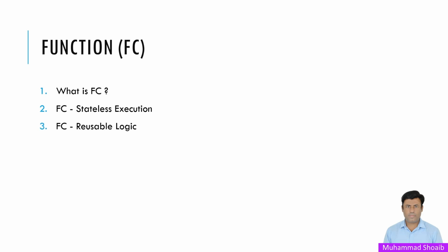In a similar manner, FCs are reusable logic. FCs allow you to encapsulate frequently used logic in a block which can be called multiple times in the program, like FBs. We can also call an FC multiple times in the program. FCs require no instance data blocks.